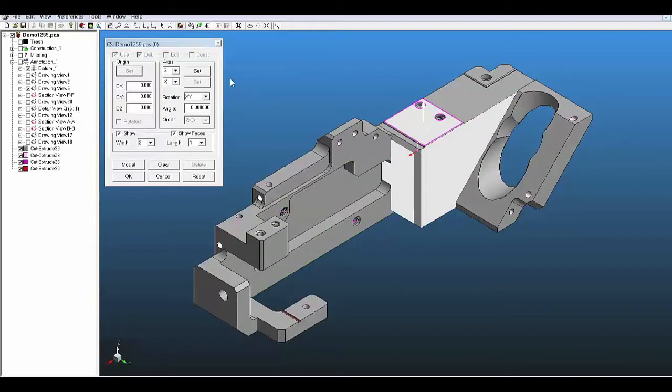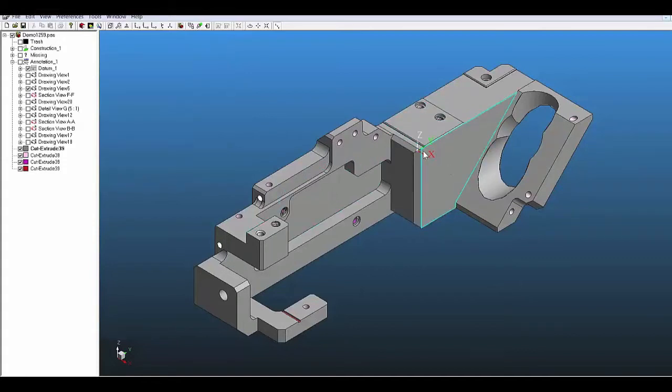Now we're going to set the Z and then set the X. But not to be confused with the datums. The datums are brought over from SolidWorks and they are measured and analyzed independently. This is simply just to set the part up on the machine itself. We say OK, and now our coordinate system, X is going to the side and Y is going to the back.